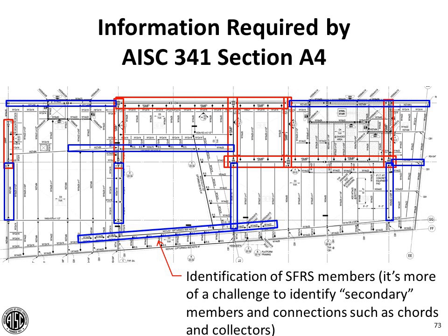Now most of these members are the drags or collector members that connect the rest of the structure to the seismic force resisting system. As you can see in this building, it's not necessarily very seismically friendly, with that nice big opening in the diaphragm, and the fact that all the frames ended up having to be located in the upper portion. And so there were a fair number of elements that were designated. In addition, there are also bracing requirements, and I'll show that in just a moment.